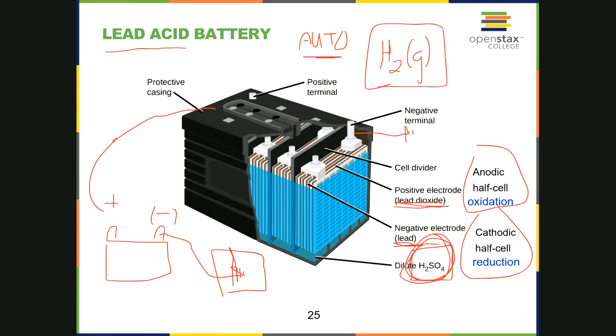Definitely do not attach positive to negative between the batteries. That will destroy your battery, probably destroy the other person's battery, seriously mess up your automobile. Once you have them hooked up, then the person that has the good battery can start their car and give it a while then for your battery to be pulled up to where it can then start your car. Okay, just wanted to take this opportunity to keep you guys safe.